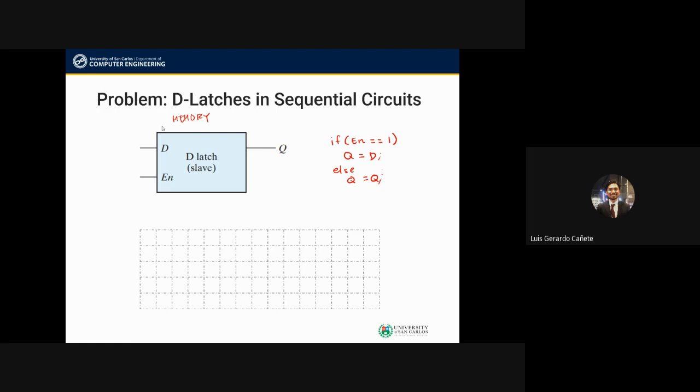That's what you're really saying when you say I have 1 gigabyte of memory, because 1 byte is equal to 8 bits, and every single bit, since this can store 1 bit of information, just 1 or 0, means you have 8 D latches for 1 byte. So 1 gigabyte would mean that you have 8 billion, right? Because giga is 10 to the power 9. So just a little bit of information for you. Inside your computer, there are billions of D latches that basically function similar to how this is functioning right now.